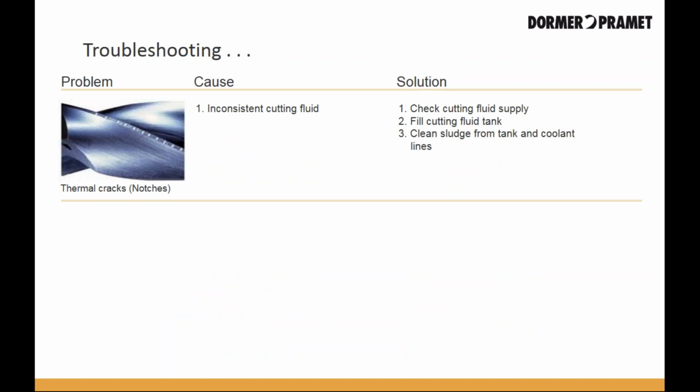Thermal cracking. If the coolant is sputtering, the temperature of the drill can go way up, and a splash of coolant will quench the carbide, causing cracks. I like to relate this to letting a piece of glass heat up red hot and then dipping it in water. It's going to crack and it's going to break.